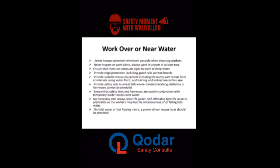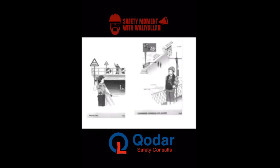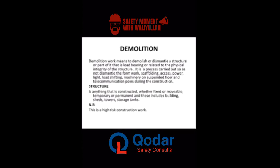How about when working near water or over water? It is assumed that we need to have a standby rescue vest. We also need to have a lifeline, a combined life jacket, a good harness life jacket. We also need to have an emergency line. We also need to have all our complete PPEs. This is going to help us work very well near and over a water line, a bridge construction, or near any form of water body.